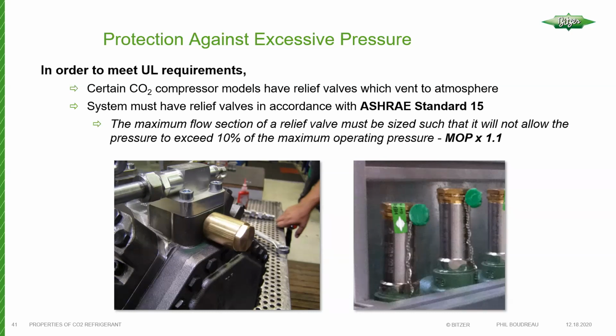So the relief valves that are on the system, okay, we have to remember those relief valves have to be there. Never assume that when you see a relief valve on a compressor that you can use this in lieu of the system pressure relief. The valve is sized to prevent the casting from overpressure in the event that it's been isolated inadvertently.